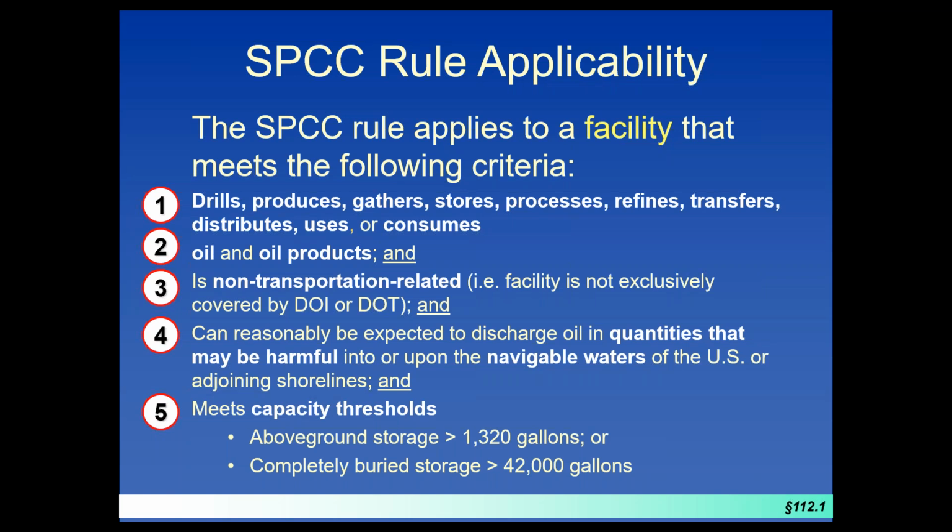Now, completely buried is a little bit different in that a majority of our regulated tank universe is now exempt, because what we say is if you're regulated under the UST program, SPCC doesn't apply. Typically for a locality or tribe, a UST that would fall back into our program would be something like a consumptive use heating oil tank. That's an oddball underground storage tank that may fall back into our jurisdiction because it's not regulated by the UST program or by a state equivalent program. So that gets a little tricky, but for the most part, the threshold that's typically triggered is greater than 1320.